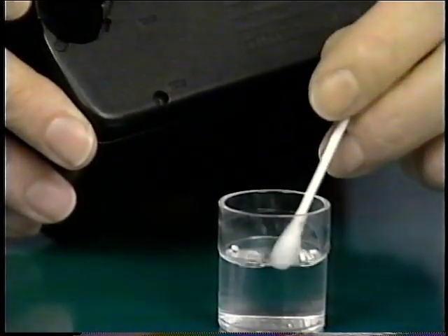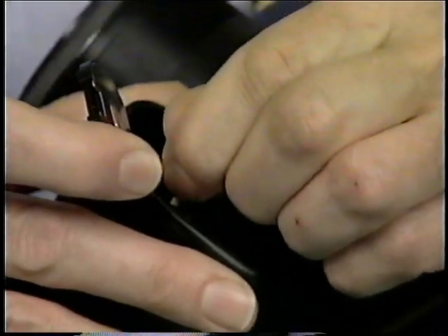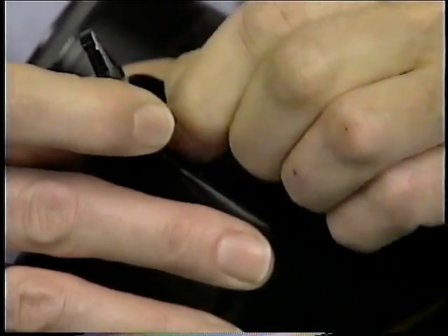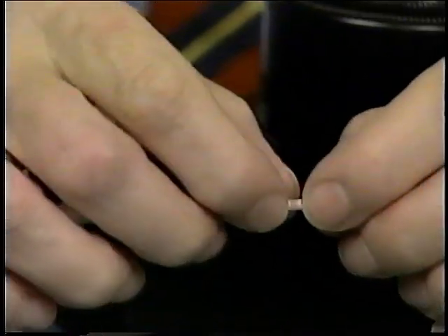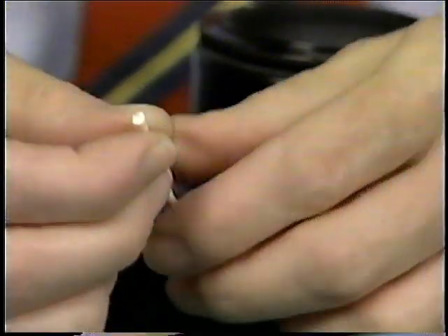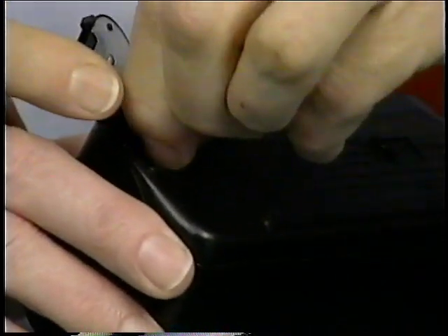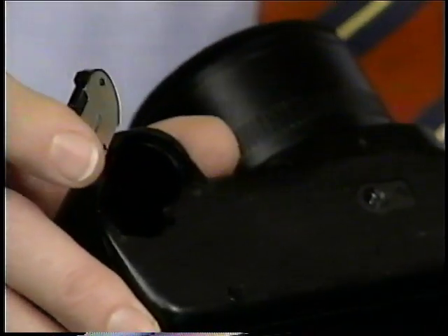We use just a little bit of isopropyl alcohol. Remember, this is 91% isopropyl. And then just go inside and carefully wipe off the ends of the battery terminals. If it looks like there might be something on there which is giving you a little bit of trouble, you can break a Q-tip and use just the paper end. In other words, the frayed paper makes a pretty good cleaner, and you can work that against the battery terminals and usually take off any stubborn films that are on that way.